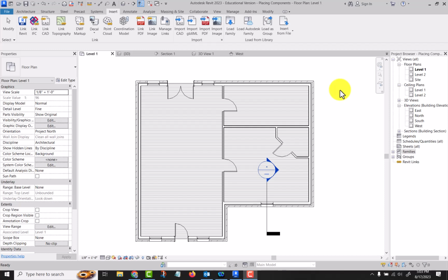But all families start with a template. Is it a wall-based family that you're going to create? Is it a floor-based family you're going to create? Is it a ceiling-based? Or is it just level hosted, meaning it's not floor based? It's a non-hosted component, but it could be horizontal, it could be vertical, depending upon the template that you use. And then there's the truly non-hosted ones that could be put on any surface, horizontal, vertical, angled, things like that.